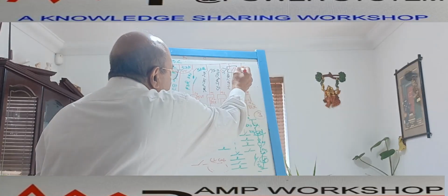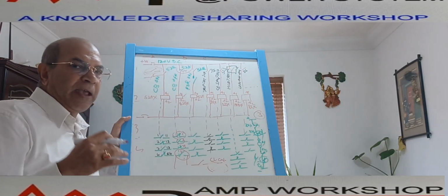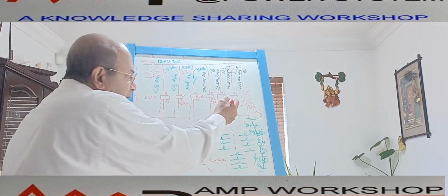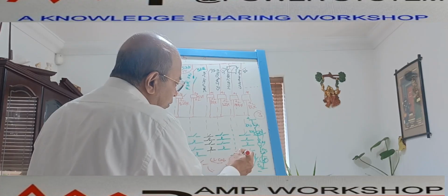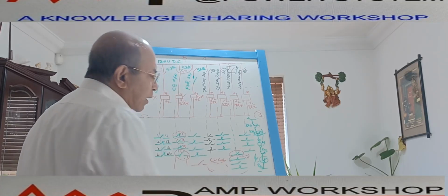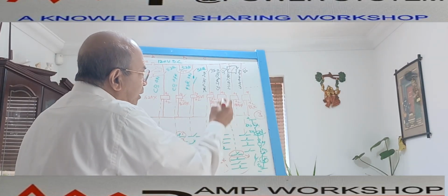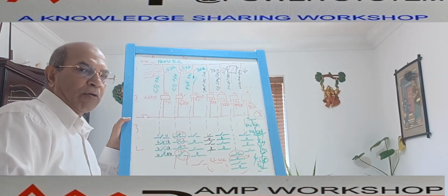So all these contacts we connect in parallel over here, and then we put an auxiliary relay that will give any of the MCB trip conditions. When we get this, this MCBX will energize. The MCBX has multiple contacts. Suppose one of the NO contacts we are using for the control panel. The moment this relay energizes, meaning when the MCB trips, it will immediately give an indication in the control panel.